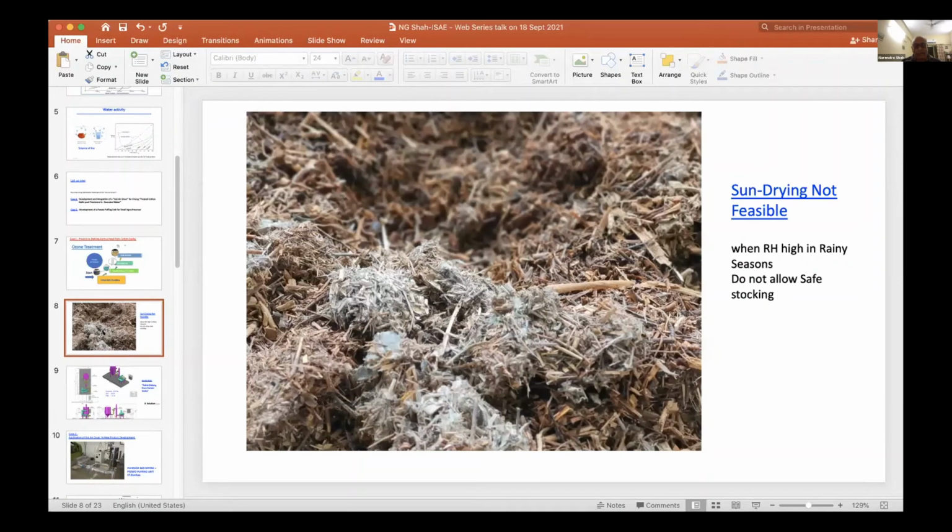Even in a dry district like Pune in Western Maharashtra, it doesn't rain like Konkan or Mumbai. Look at the fungal attack that you have on the treated cotton stock, because the treated cotton stock, which is removed from this ozonated water, has an initial moisture content of something like 85%. And we need to bring it down to 15%, because the briquetting machine has to work. And the briquetting, with other ingredients like oil cakes, which we make into a complete feed, has to be brought down from 85% to 15%.